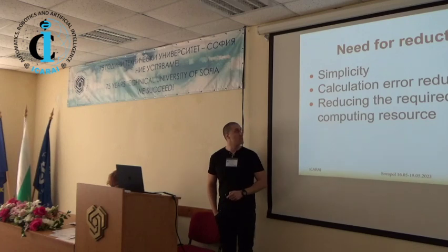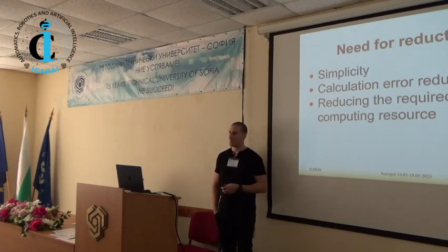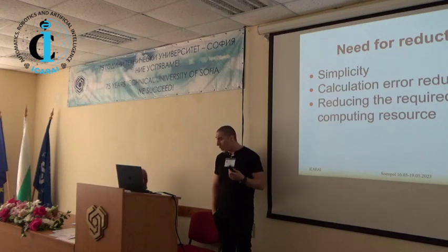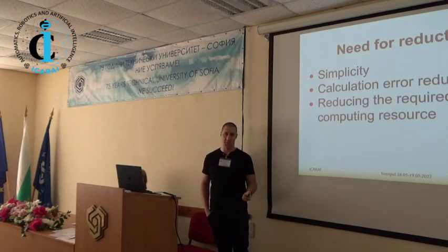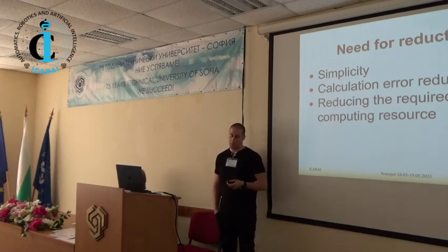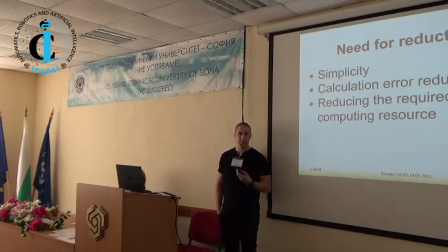Here are the points that I would like to address in my presentation. First, the need for reduction. We know that controllers designed using the H-infinity norm lead to a high order, which is equal to the order of the plant itself plus the shaping filters. But is it always needed to use this complexity, this high order? Maybe not. If we can reduce the order of the controller, there might be some benefits.